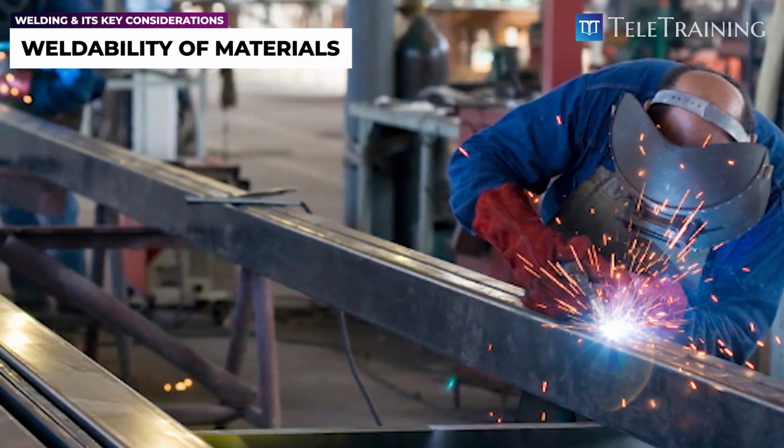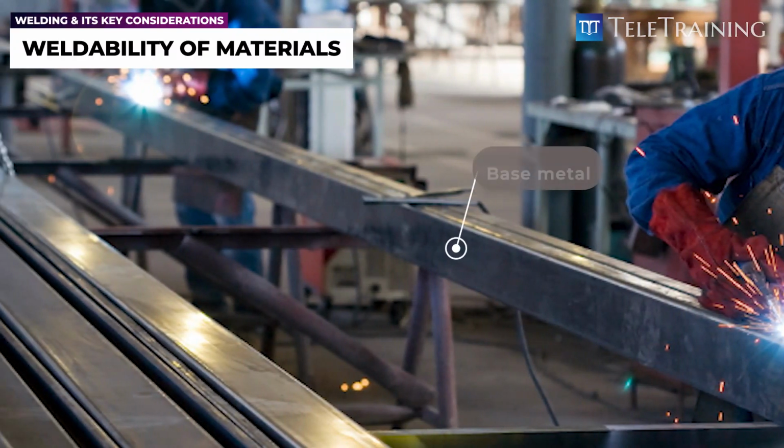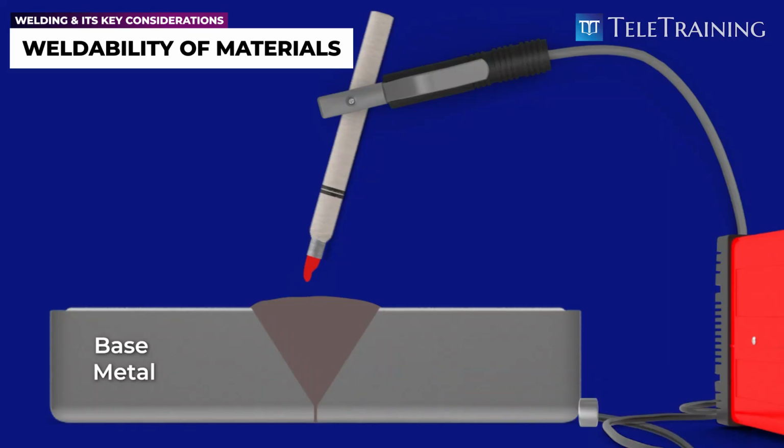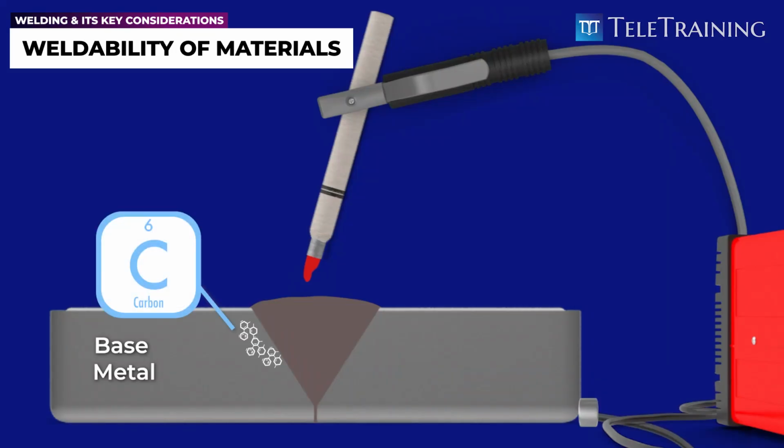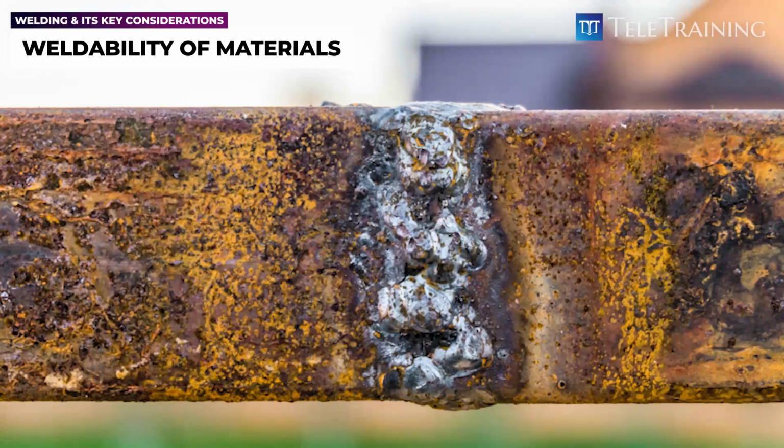The first factor to consider is the weldability of the base materials. For example, if the base metal has high carbon content, the parts may not weld properly, as these metals are crack sensitive, and their mechanical properties could change significantly after the welding. For example, older structural steel may have a high carbon content.